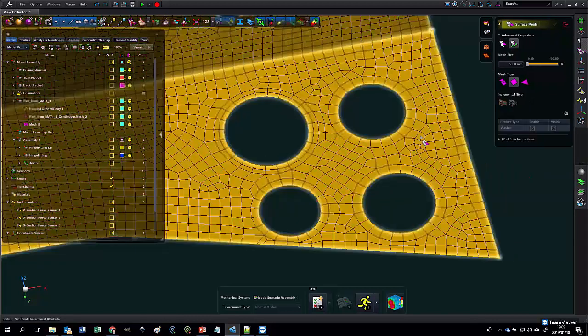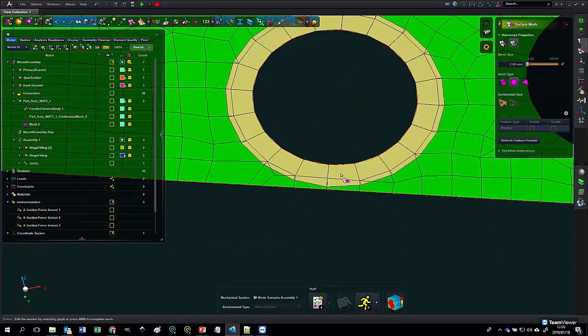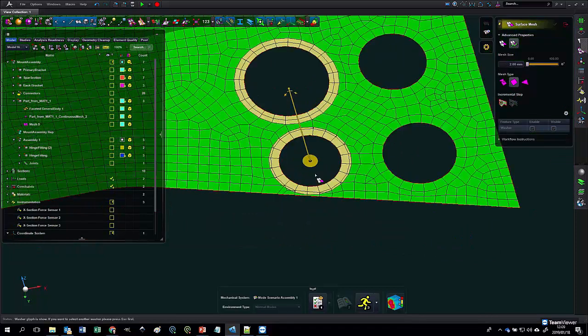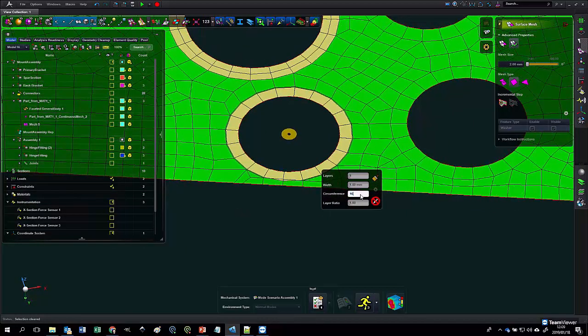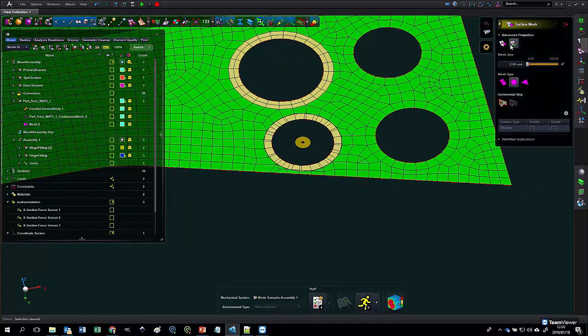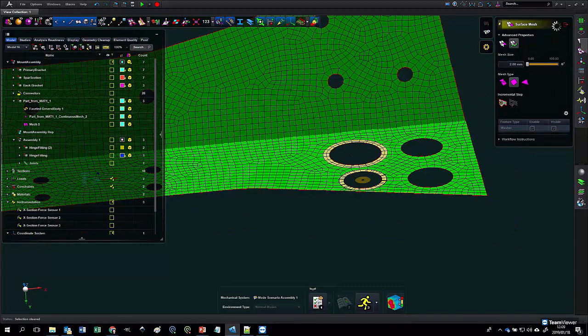So using this incremental method is quite useful because now, as I said, we can work on one washer at a time and manipulate these various aspects of it and see what is probably a better set of values to use before we actually apply it, or maybe apply it for the rest of the model. But this is a way to individually deal with washers.